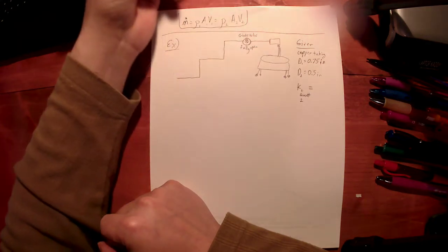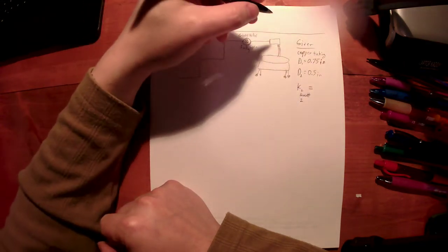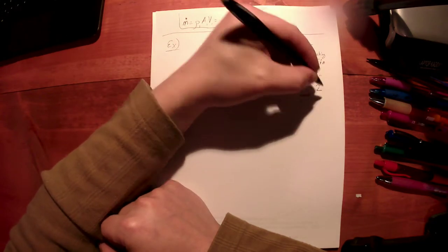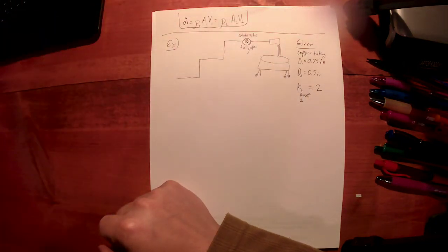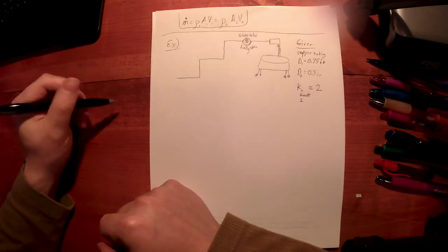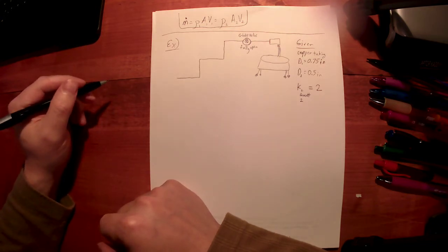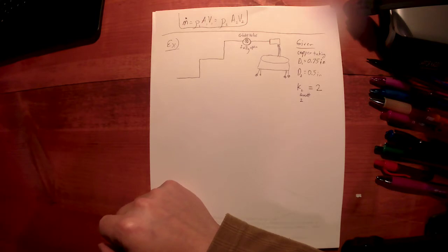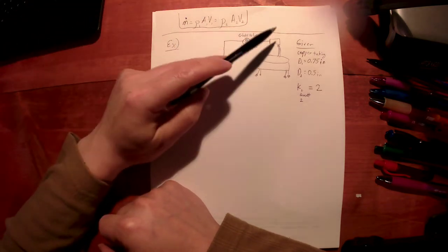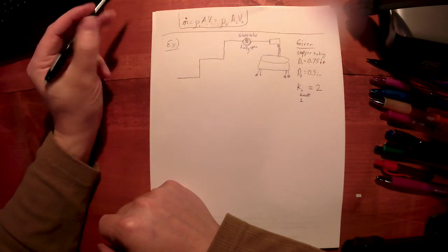So the minor loss coefficient at 0.2, we're going to call that simply K2. Sometimes if it's a weird fitting, we'll have to go look that up. Or maybe somebody will measure that for us. Maybe we get that from the manufacturer. Some way of trying to find it. Okay, so we get a minor loss coefficient right here at this faucet of 0.2.